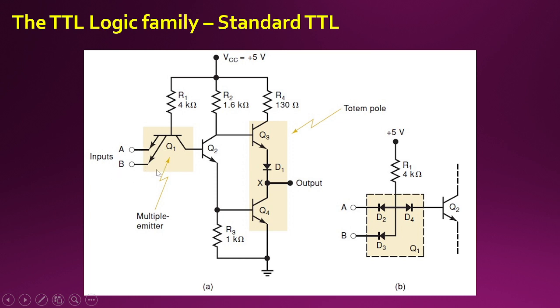Now, if we go for a diode equivalent model, you can see this is N, P, N. If I consider just one, then I can draw a diode where N type is A, P type is connected here, again B is N and P type is connected here, and this side again we have a P and N. So we again have a diode in this fashion. This particular Q1 transistor can be replaced by a diode equivalent model, which is given here.